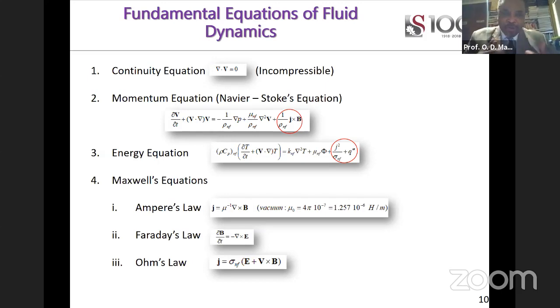So continuity equation, that is continuum, which means if a fluid flows into a tank and another fluid flows out, for you to know the amount of fluid in the tank, you subtract the one that goes out from the one that is coming in. You know the amount that's already in the tank. So there is continuum. You cannot have a vacuum. That's the continuity equation. And when the fluid is incompressible, which means that we are talking of hydrodynamics now, we are talking of liquid dynamics, when the fluid is incompressible, then you are basically saying the density of the fluid is constant.